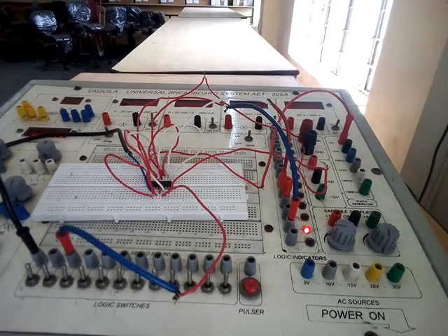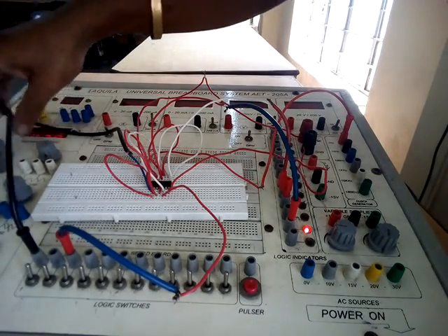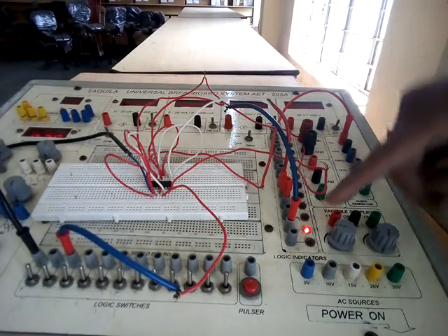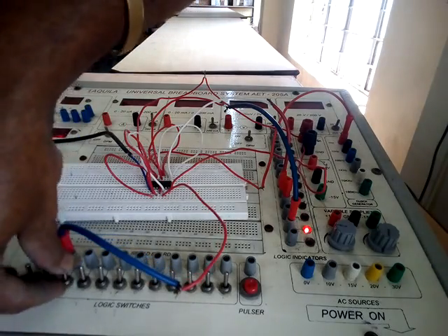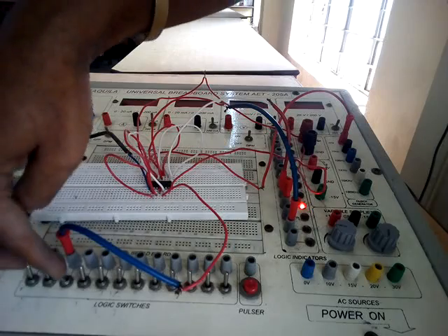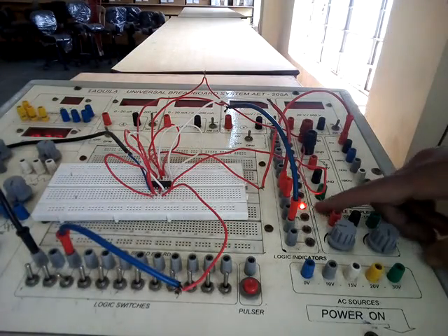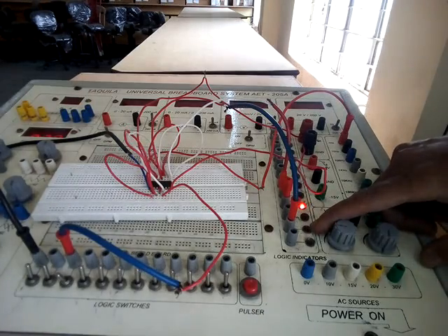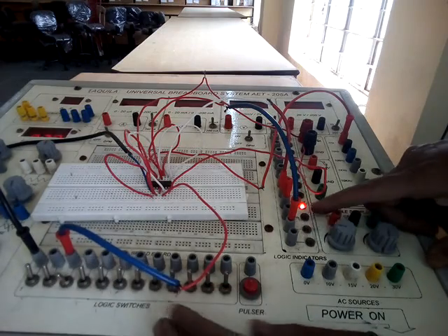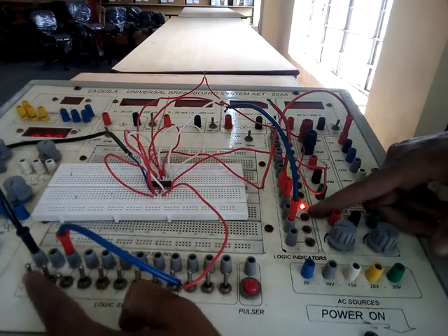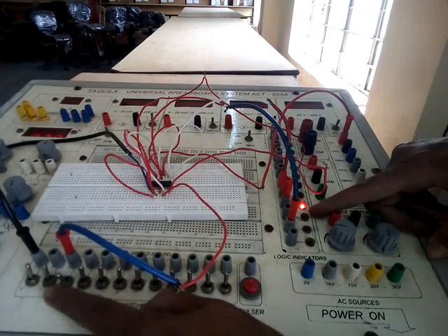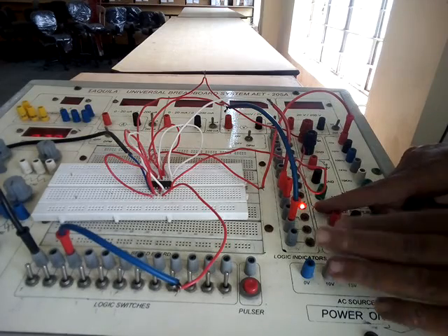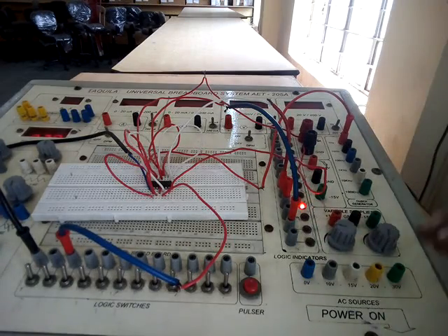Okay, first of all, it is S, which is going to pin number 1, and it is R. It is Q and it is Q bar. So if we give R 1, then it will be reset. That means Q bar will glow, Q will be off. And for 0 0 condition, there will be no change. If we give 0 0, it is 0 and it is 0. You can see no change. The previous state is stored in the memory.